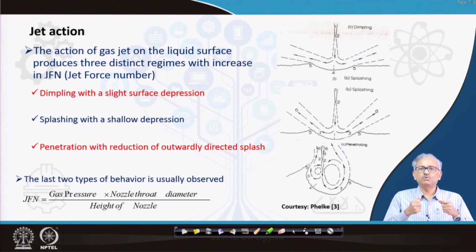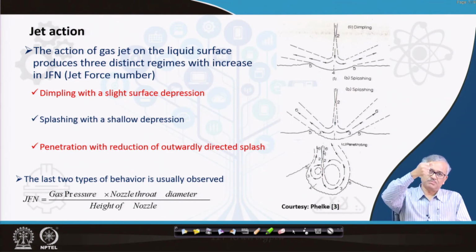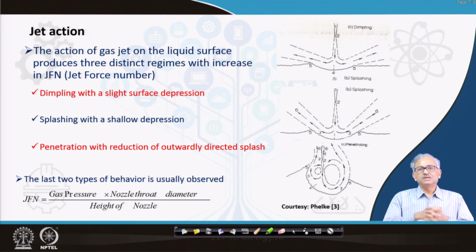In the case of the soft blow, what happens? You decrease the GFN by taking the lance away from the bath. So you can decrease the GFN, and when the GFN decreases, your rate of formation of FeO becomes more than that of decarburization. That is, you can build up the FeO in the slag, and that is sometimes required. I will talk about that. That is the slag practice people do. You build up the FeO by suppressing the decarburization, and this is mainly done when you have